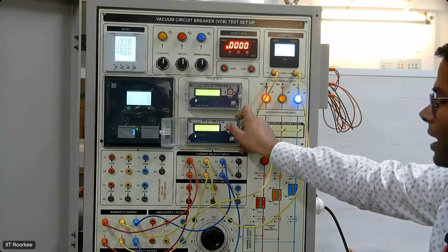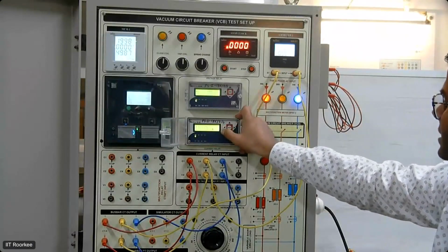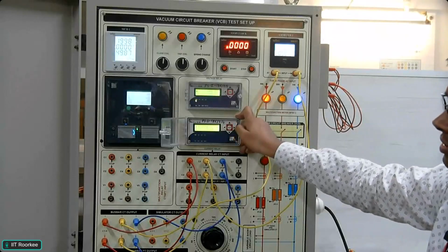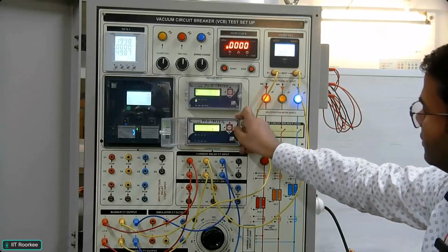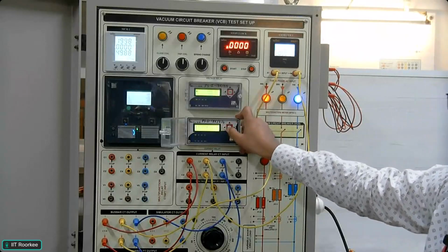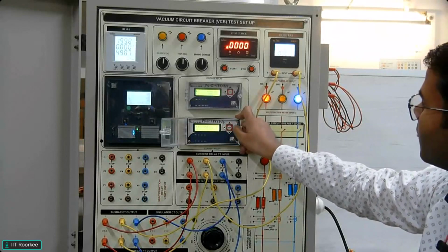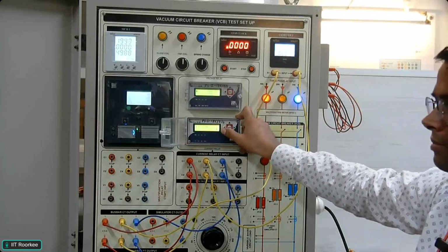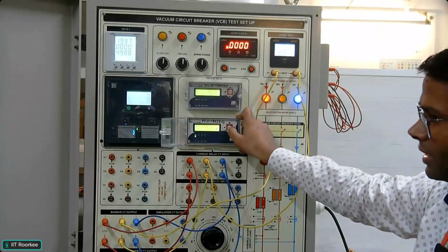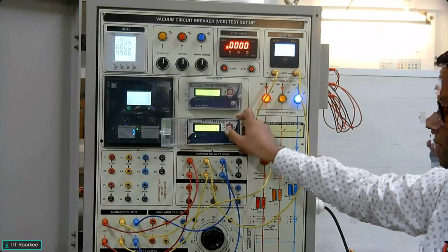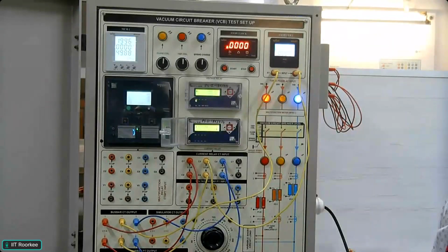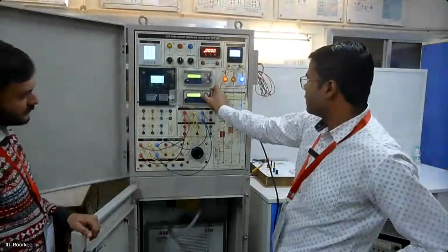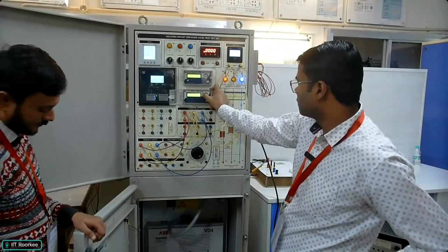Next, this is the plug setting. The plug setting is 20%, and IN is the rated secondary current of the relay, sorry, not the circuit breaker. Here it is 5 ampere. This is the time dial setting, which is 0.7. And this is the time for the definite minimum time characteristic, so the time will be fixed. Here it is taken as 10 seconds, because the spring charge will take nearly 5 to 6 seconds. Now it is set to normal inverse 3.0.